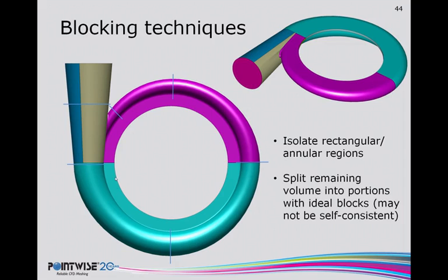That would be very simple and straightforward to mesh. You can then also say, okay, well, these segments of the scroll could also be meshed individually and would be fairly straightforward. It's just a circular cross-section, albeit one that's changing as a function of the angle around the volute. But generically speaking, that's a fairly straightforward topology, and we'll actually mesh this in just a minute. So that really reduces this entire geometry to one area here near the tongue.